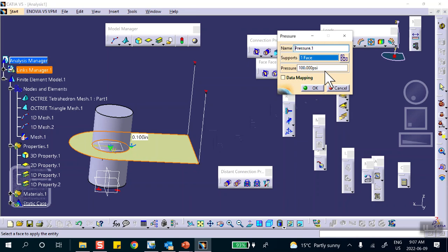3,000 pounds is 1.5 ton. Okay, it's almost the weight of a car, a small sedan. And remember, this is steel. Okay, I understand that. But it was 0.1 inch thick. So just be aware of these things. I'll give you numbers that may be totally useless because the stresses may be so high that the material is not going to be linear elastic.